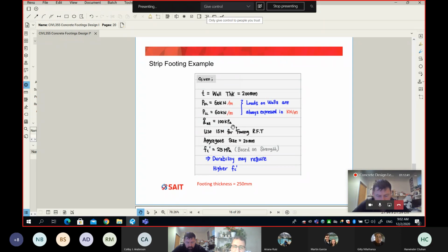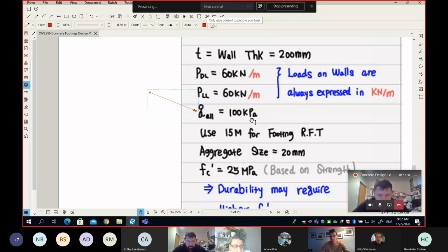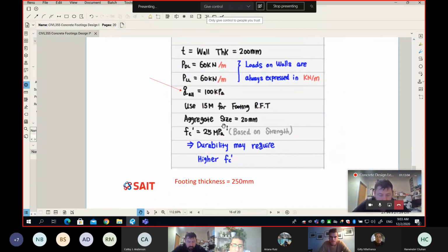Now, my geotechnical engineer gave me the Q allowable. Please watch this, very important. My geotechnical report did not provide Q factored, it provides Q allowable, which is 100 kPa. Also, we are going to use 15M reinforcement. The aggregate size is 20 millimeters. The f'c is 25 MPa.